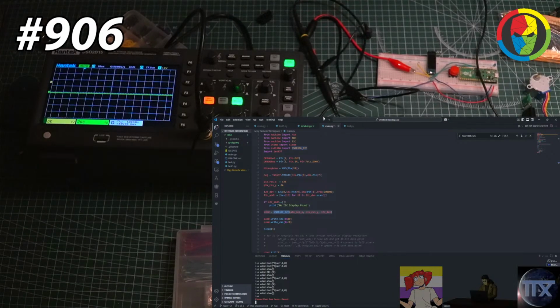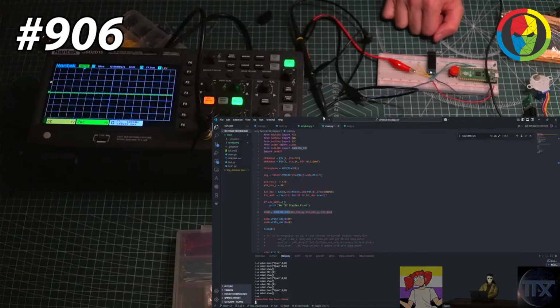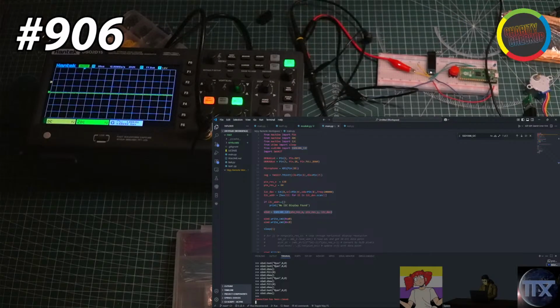I've never tried to read a USB connection, but you'd probably want to do like a man-in-the-middle attack while it's communicating with something. Yeah, I imagine with any kind of connection you prefer to do that. Unless we look up what we need to do to those pins, because maybe we need to pull them low or high to trigger some kind of response from the computer. But we'd almost have to reverse engineer the USB protocol. Ideally we'd set up some kind of normal connection with something and then only measure that connection. Yeah, that or a UART connection. Can you do USB to UART? You could read the output of that.